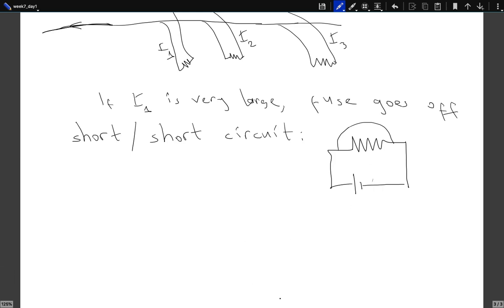Now, these shorts usually happen, for example, if you look at this wire. It's quite thin. Some part of it will bring the current into my computer. Some of it will just take it away from my computer. But if I step on this, I can just break the insulation between those two wires. And rather than going through my computer, the current will just go through that short, causing the fuse to go off.